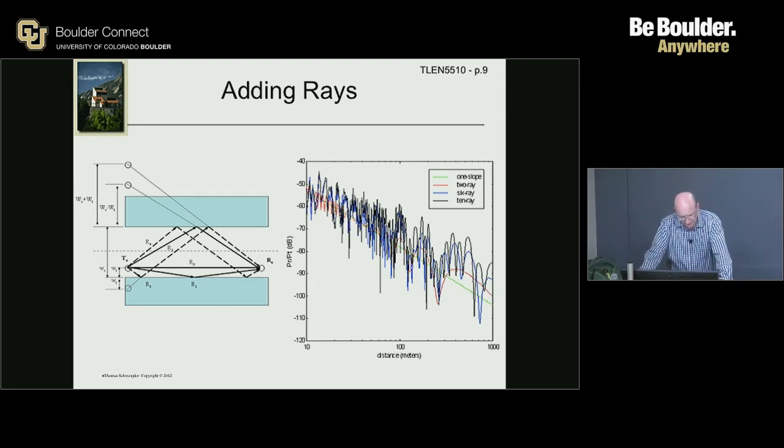consider R0 from the transmitter here to the receiver here. R0 really hides 2 rays, right? The direct one and the one that bounces off the ground. But you can't see it because this is the view from above. So now consider R1 bouncing off a near building from the transmit to the receiver. Again, there's 2 rays hidden behind R1. The one that you see here, transmit to building to receive, and the one that you don't see, maybe it hits the ground here or maybe here, but it's perfectly vertical with that one. And so that would be a 4-ray model.